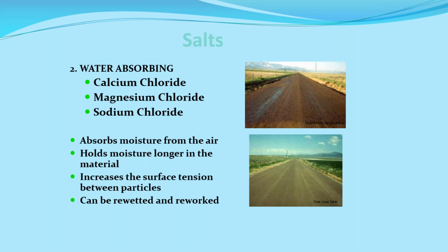Okay. Now, with all three of these salts, as a prep, the roadway has to be wet. If the surface is wet and the underlying material is dry, that magnesium, calcium, and sodium will only drop down into that roadway as deep as that moisture is. If they hit a dry layer, they'll stop. And that's as far as they'll go, as far as stabilizing. And ideally, you want to get that material down an inch and a half, 2 inches maybe, into that material. So you need to make sure that you have moisture below that 2-inch level.